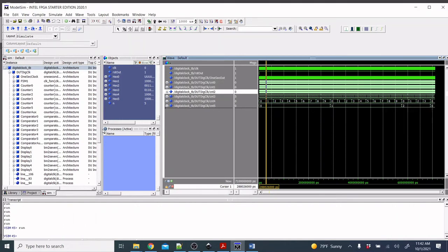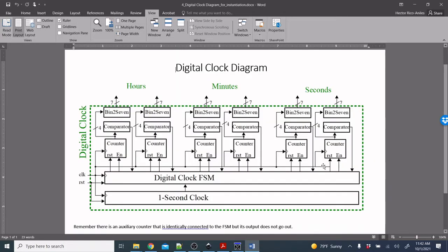How to debug that is as we did with the counter. If something is not giving the value we're expecting, we check all the connections around that component. If all the connections around that component make sense and are correct, then the problem is going to be inside the component. Maybe we find the error that is outside, like in the case of the reset, where it wasn't the component itself the problem, it was the connection we had here that we were not resetting with the global reset.